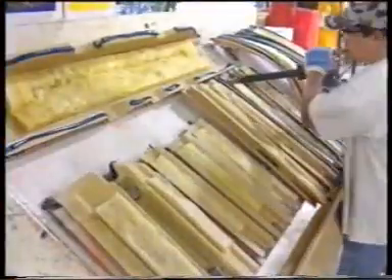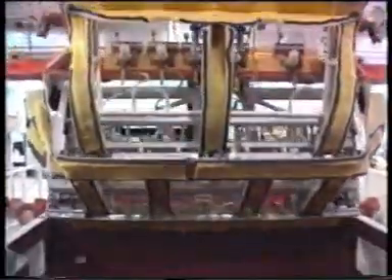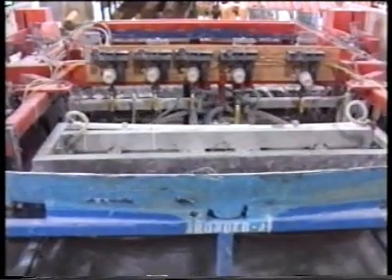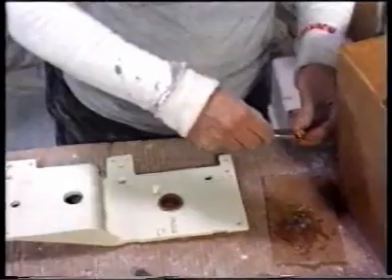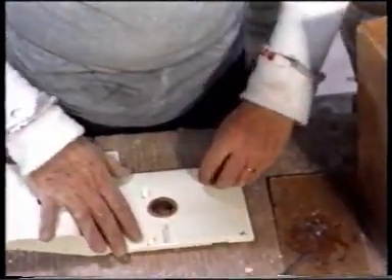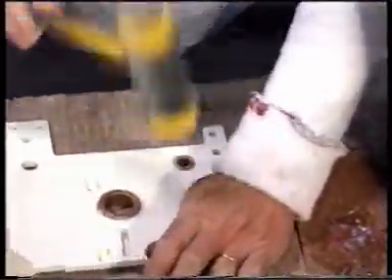After the adhesive is applied, the workpieces may be placed in a fixture and then pressed together to remove trapped air and cure. Some adhesives cure at room temperature, but many require elevated temperature. Adhesive bonding can also be used to bond surface-mounted fasteners and bushings, thus combining adhesive bonding and mechanical fastening.